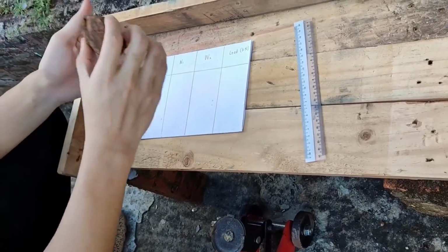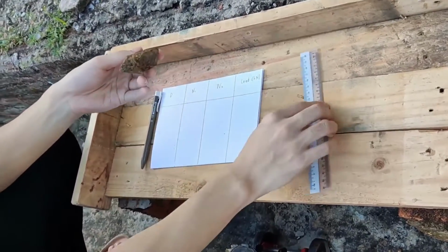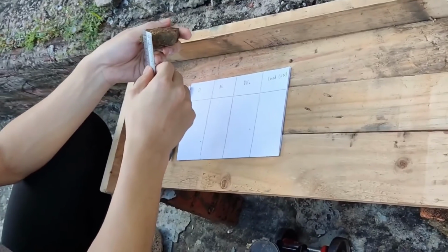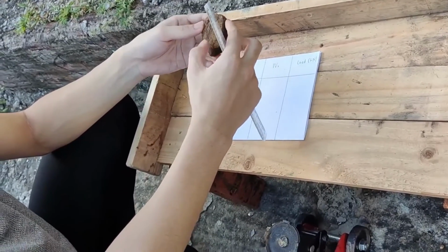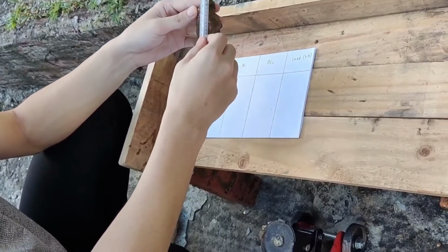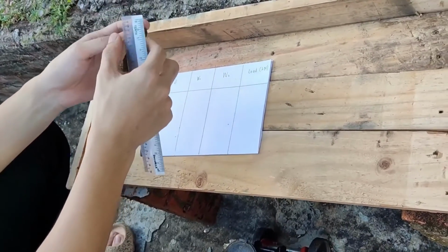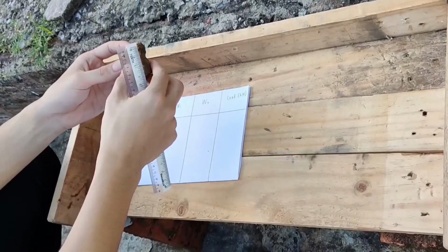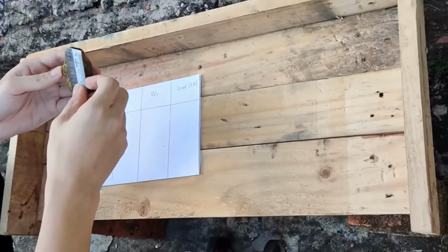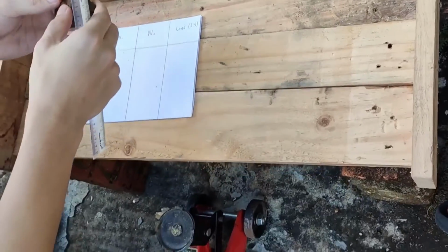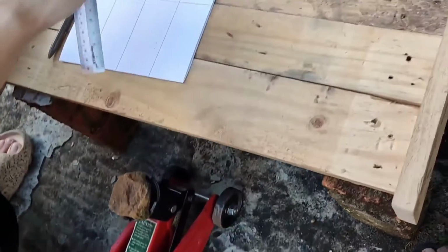For test 1, this is the rock sample that we are using. The depth that I will be measuring will be here, which is 24.62 mm. Then the width perpendicular to the depth will be here. It is 32.0 mm. This is the first piece. The second width will be at the bottom, which is 31.98 mm. After measuring, we will record it. Then we will take the rock sample to the PLT machine and we will be testing it out.